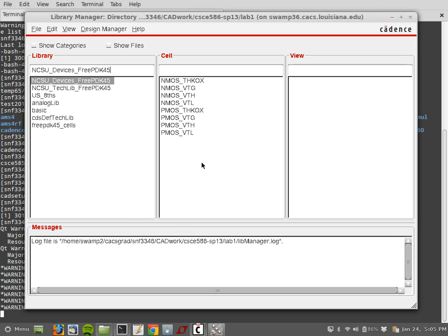Basically, if you look at the ID equation, once the threshold is lower, the ID is bigger. So actually this will give you faster transistors with VTL. Now the power will actually increase with VTL. So you're increasing the power, but it's actually a faster transistor. So everything we do is going to be VTL.